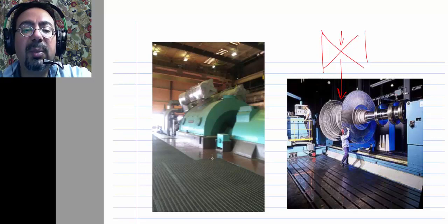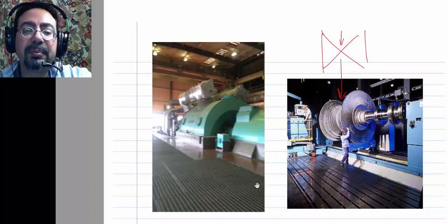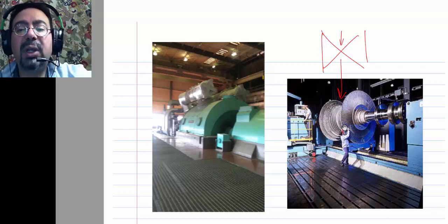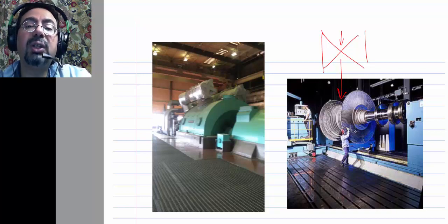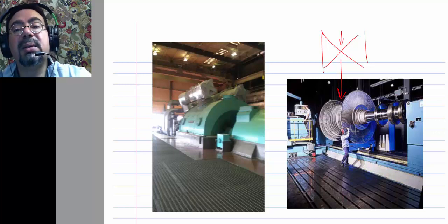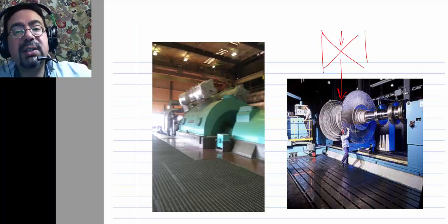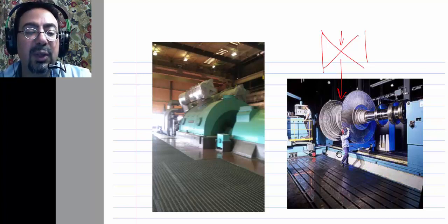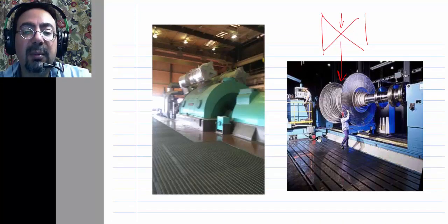Here is a sketch of the steam power plant. This is in Jenks power plant, and you can see the size, how big they are. Okay, the low pressure turbine, the one where they send steam in both directions, that's how it looked. You can see how large those plates are, and you can imagine how much larger they would get if they had done this in one pass. They would be ridiculously large. The centrifugal force would just snap them out because of the speed they are running at. So that's why they break them into two, setting them back to back.